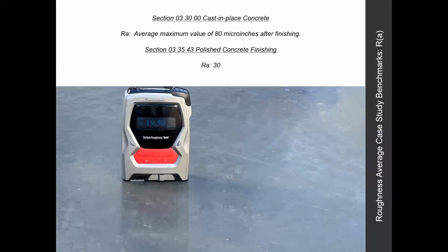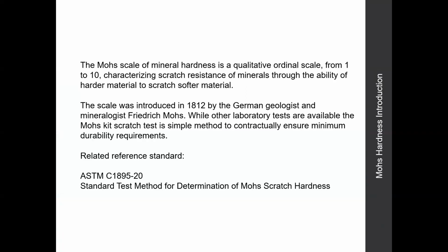And so they said, well, hey, no problem. We're going to come back here with grout coats and we're going to do all this kind of stuff. And these are all change orders. This is all degradation that's going to be a legacy issue for that surface. And so being able to walk them through not needing to use grout coats, not needing to use these sort of patch Band-Aid materials, and refining the concrete mechanically and chemically to meet these benchmarks really helped them be more efficient. And it helped them make more money. So the owner gets the schedule savings, but they also benefited directly because their labor and material costs went down.